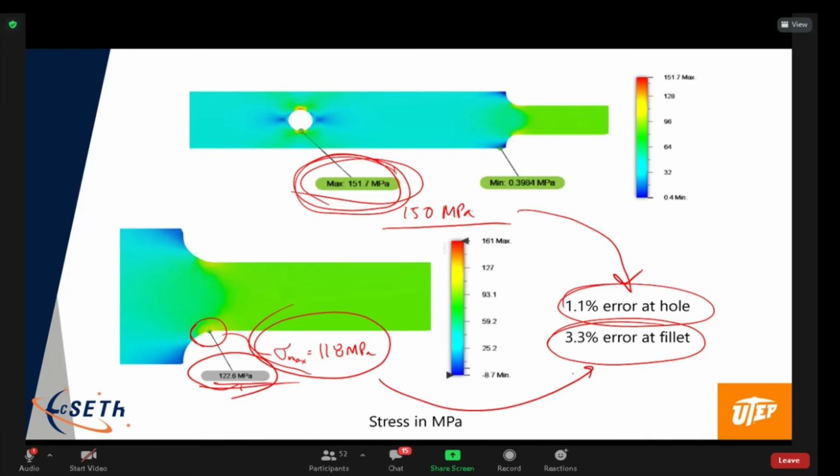But the real point I wanted to make is that, in general, for an engineering hand calculation, typically, if you can get a result within 15%, very likely 25%, you're doing real good. That's really good because the assumptions are really crude for hand calculations. In this particular case, we do pretty well because the hand calculation is basically exactly what's going on geometrically here, right? There's nothing else weird going on, no other assumptions went into there.